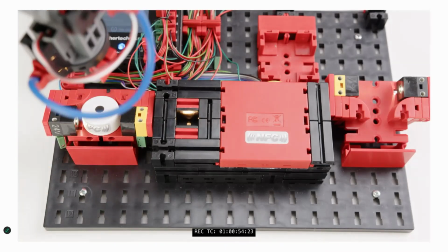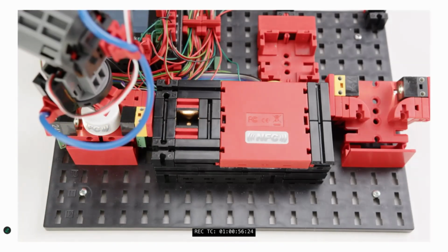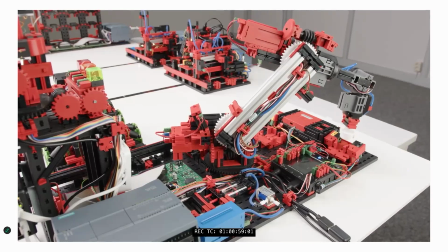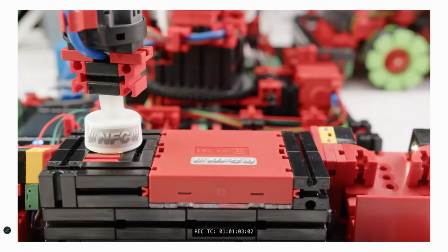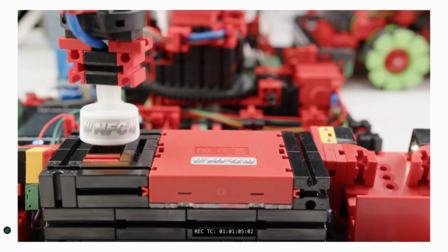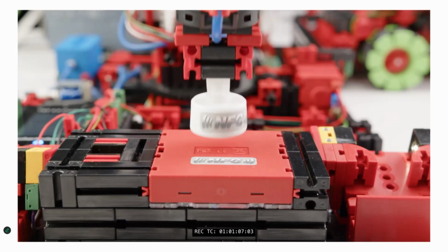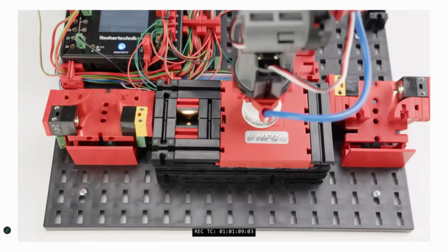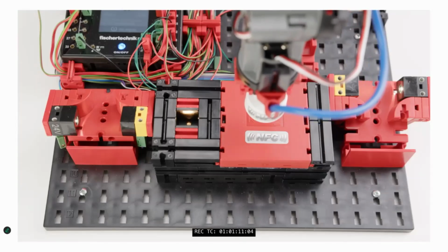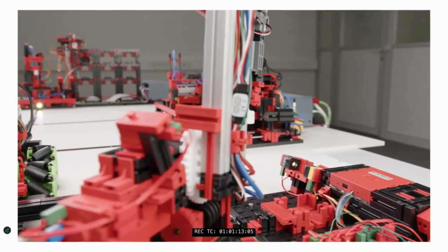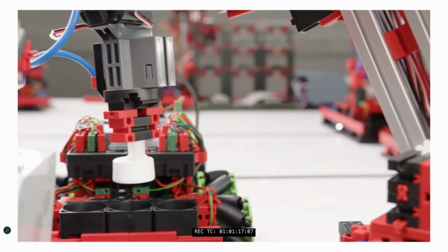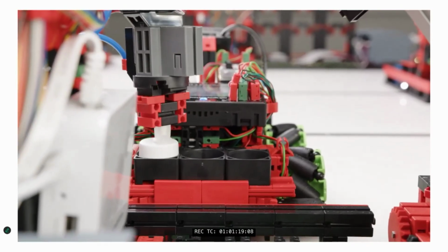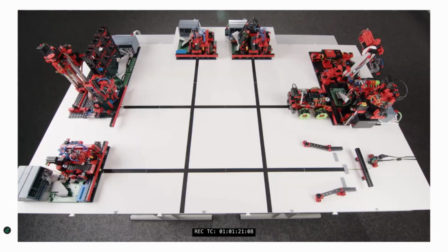Here you have a workpiece being entered into the station where it's going to get scanned by the NFC reader and entered into the system. Once it has been, the 6-axis robotic arm, which has the vacuum gripper right now, is going to take that piece and move it onto the AGV in one of those little slots in the back, which you'll see happening here. And there you go.